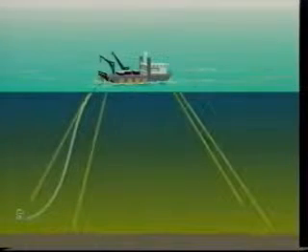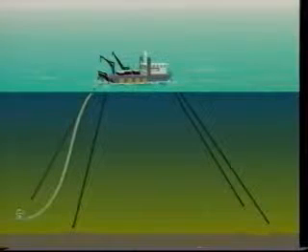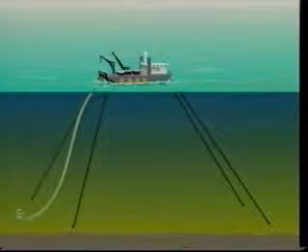Offshore flow lines are assembled and installed with the use of a special lay barge. These barges are anchored to the seafloor and assemble the line at the surface. The barge can continuously move forward, allowing the line to sink. These barges are equipped with all the necessary stations to store, weld, inspect, and apply corrosion protection to the flow lines.